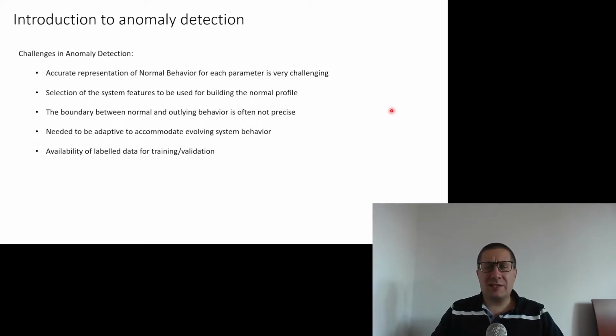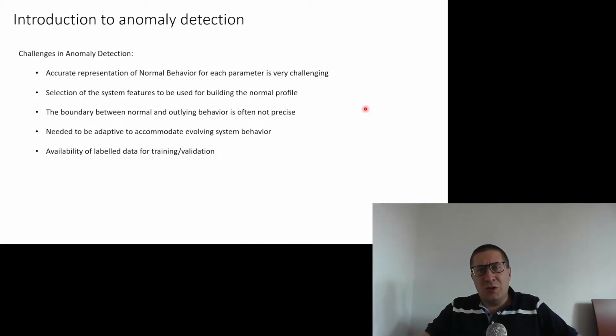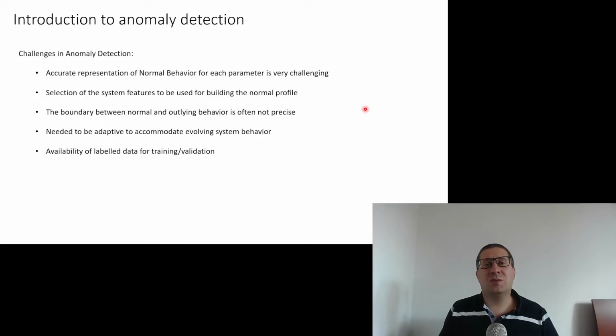If we create an algorithm that will simulate the normal behavior, so the algorithm that will predict the values of process parameters, assuming the normal state, and we use this algorithm to detect anomalies in 1, 2, or 3 years, probably it will not work. The current definition of normality will not be up to date in 2 or 3 years. The process will operate in a slightly different way than today. So our definition of normal behavior also needs to be updated once in a while, or we can try to apply some adaptation mechanism that will adapt the algorithm on the fly.